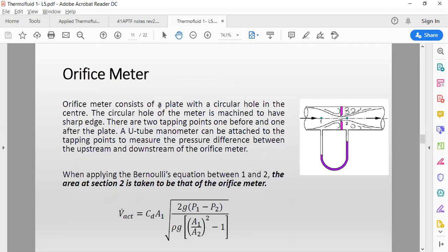So for orifice, the concept is the same. If you remember hearing me say, the principle is the same. The principle is I must create a constriction. So this here is my constriction. Can you see? But instead of a gradual constriction like your Venturi meter, which is a gradual one, today what we put here is my orifice blade or plate. Basically it's a plate. This pink thing that you see here is a plate. This plate has a very sharp edge, and it also reduces the flow.